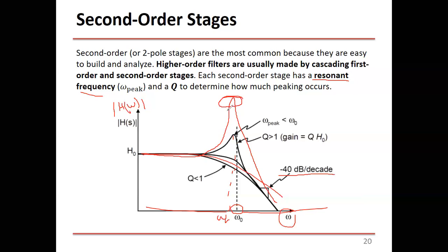So actually, here you are designing a high quality. This is why Q is called the quality factor. So if you mean to design a high quality bandpass filter, you can do it with a high Q. So you increase Q maybe to 10 or 20 or 25, a very high Q. As Q goes up, you see this notch or this height goes up.